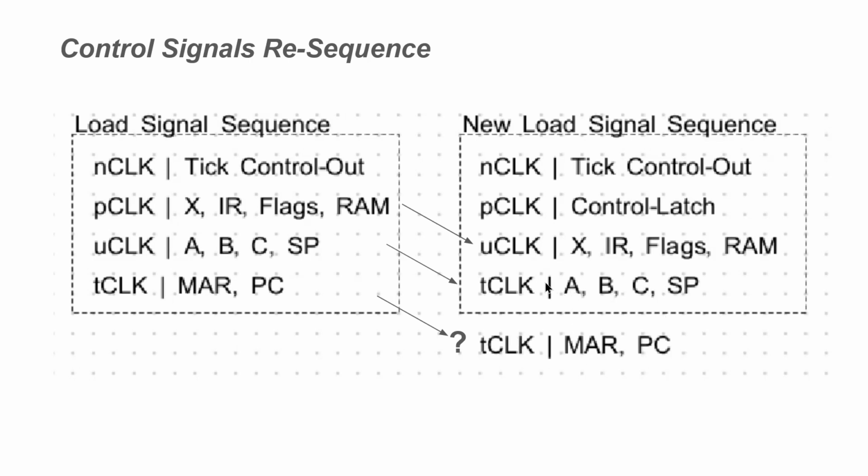So they're both going to occur on the T clock phase, but they're not going to occur in the same microcode step. So this was our first area that could potentially have been a problem, because we need to now go through all of our microcode and add the extra step for these cases where we had microcode steps doing these at the same time.